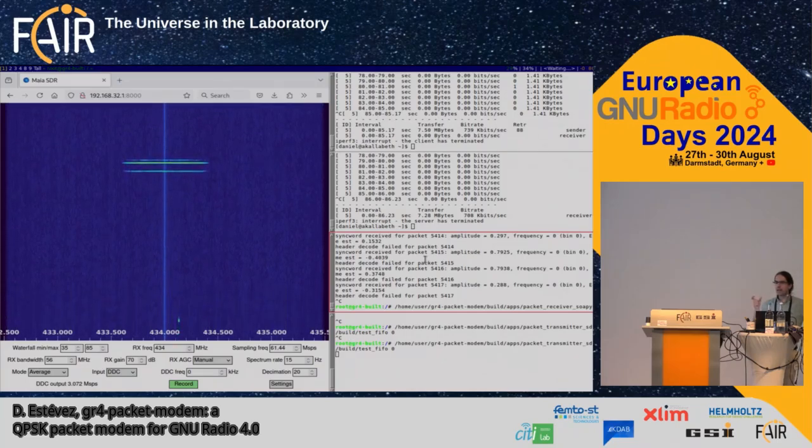Within the packet, it doesn't compensate for amplitude variations. It takes the amplitude at the beginning of the packet. So if you have a very sudden amplitude change throughout a single packet, which is short, then that packet might fail to decode. Okay. But for the rest of it, the next packet takes the correct amplitude. Do I have some more? 5 minutes? Yeah, great.